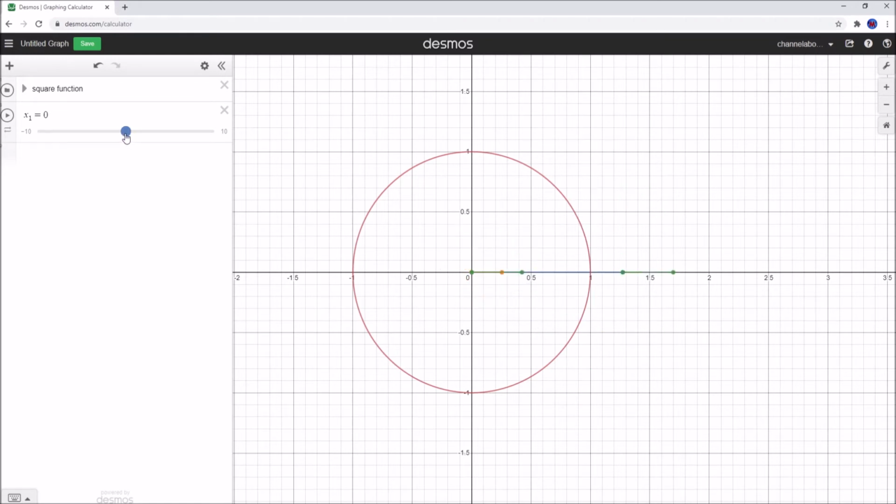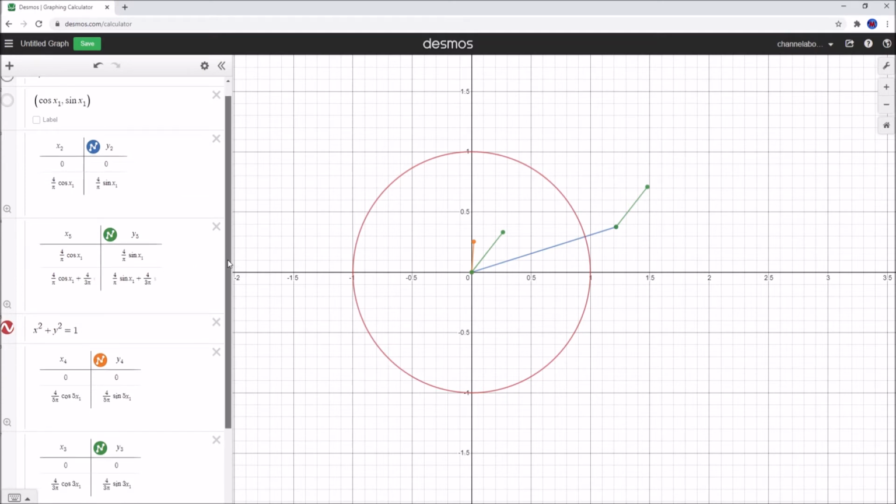Now we have to do the same for this orange phasor. The orange phasor is going to have to be added on to the end of this green phasor. So the new origin for this orange phasor is this point up here. Let's go and do that now. We have to add this phasor here onto this phasor. To get the new origin, we have to take this point here and shift it up to here. But we know what this point is because we've just worked it out, and it's going to be this coordinate here.